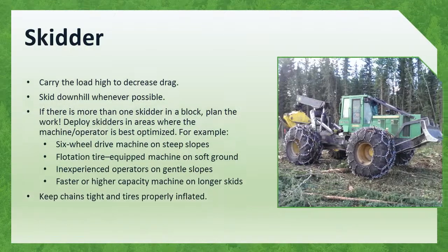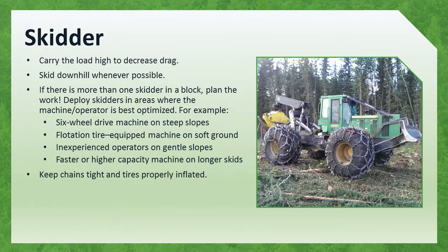Here are some suggestions for getting the most from your grapple skidder. Carry the load high to decrease drag, but provide for machine stability. Keep chains tight and tires properly inflated. Skid downhill whenever possible. A favorable 5% grade uses 20% less fuel than an adverse skid.